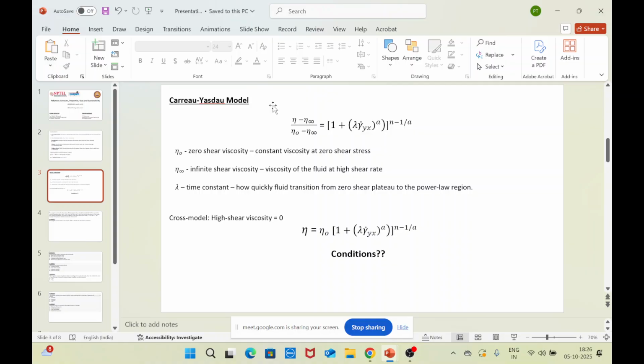Or let me also put it in another way. So the solvent molecules increase the segmental flexibility of the polymer chain. This is typically identified through DSC, the characterization technique, differential scanning calorimetry, that we discussed in the previous live interaction session.